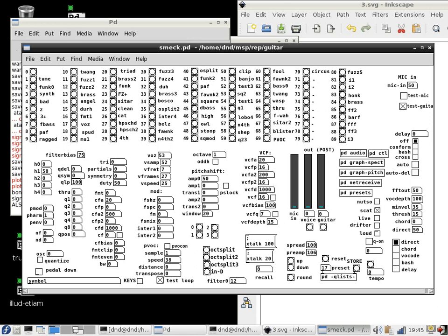And the really main reason to do that is to just assign different bandpass filters to each string. Well, actually, it's just to prevent intermodulation between the strings. So if you put even something as simple as a major third into something highly nonlinear like that, you would just get this huge difference tone instead of getting the actual waveform that you want.